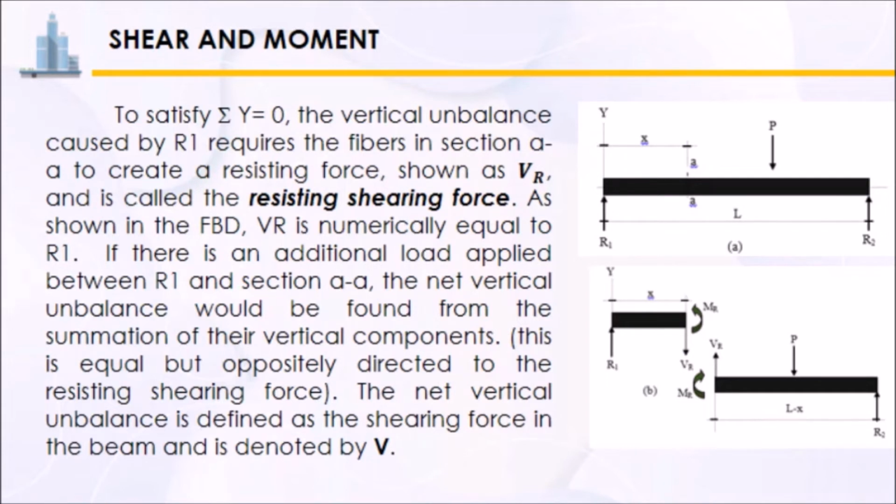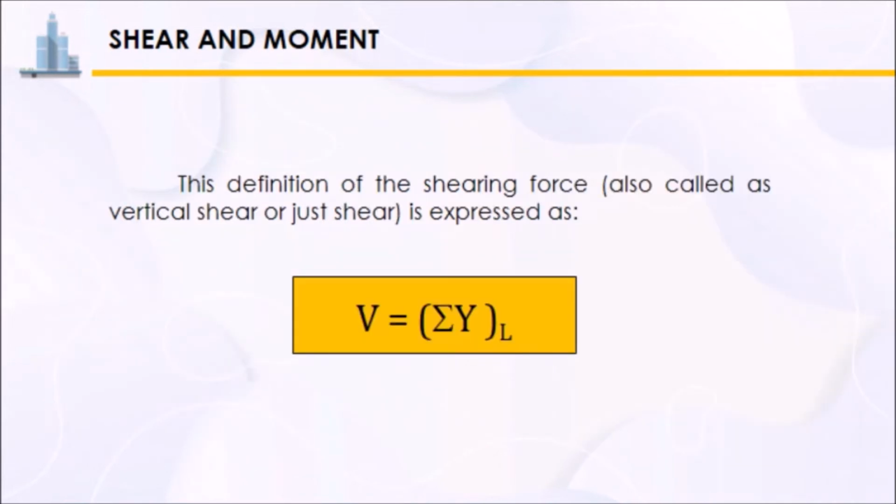So, from there, we can solve the shear. So, next naman is sa bending. Ito pa pala. So, this definition of shearing force, also called as vertical shear or just shear, is expressed as V is equal to summation of forces vertical. So, summation of forces vertical lang siya pagdating sa ating shear.